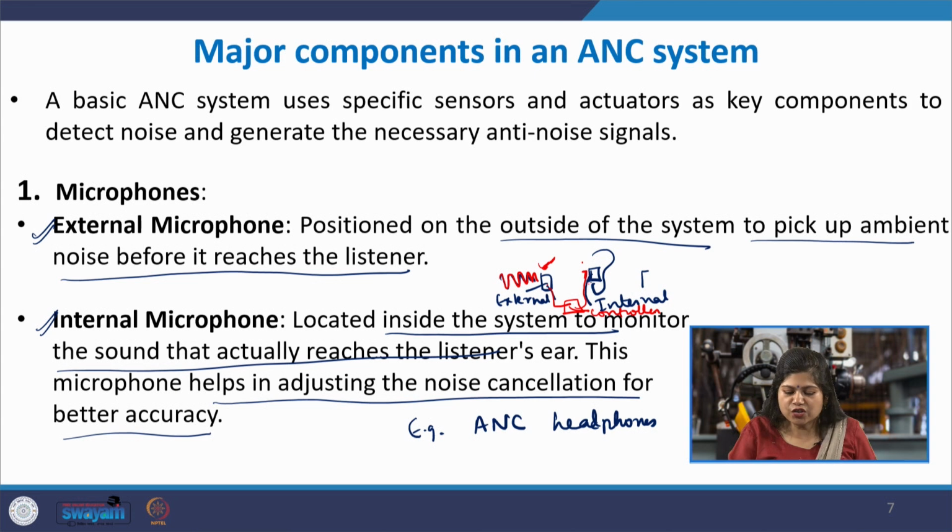So, you have an additional microphone just at the ear. When the cancelled noise comes in, this additional microphone records what the cancelled noise is at the ear. If it is 0 dB, or perfect cancellation, nothing happens. But if it is not 0 dB, because whatever was measured before the ear could have some transformations from the external to the ear, perfect cancellation may not always be achieved.